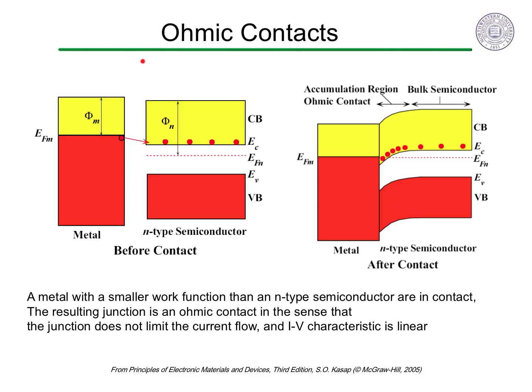For an ohmic metal semiconductor contact, we want to avoid making a Schottky junction. We can do this for an N-type semiconductor by having the Fermi level of the metal above that of the conduction band edge in the semiconductor. In this case, the electrons from the metal move into the semiconductor to raise the potential and equilibrate the Fermi level. At the junction, the Fermi level is actually above the conduction band edge, making the semiconductor degenerately doped like a metal. Electrons can then cross the junction in either direction without any energy barrier, making it ohmic and having less resistivity than the bulk semiconductor.